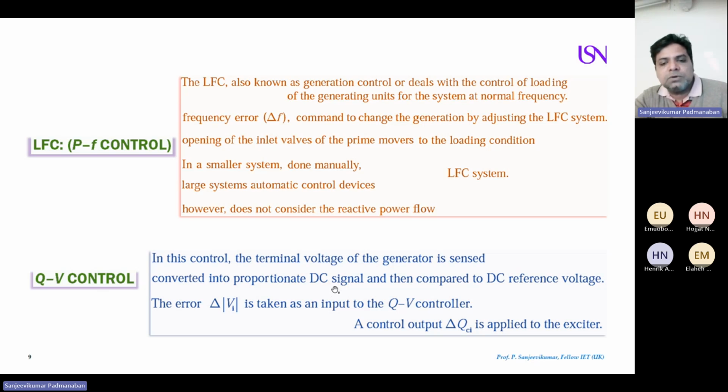So a large high voltage has been converted into a DC, which can have a very low voltage signal between 0 to 5 volt or 0 to 3.3 volt, based on the digital processor used in the application. For example, if you are using an FPGA, it's going to be limited to 3.3 volt. DSP, 3.3 volt. If you are going to use a dSPACE, it can go up to 10 volt maximum. So all the high power is converted into a low voltage DC, independent of frequency.